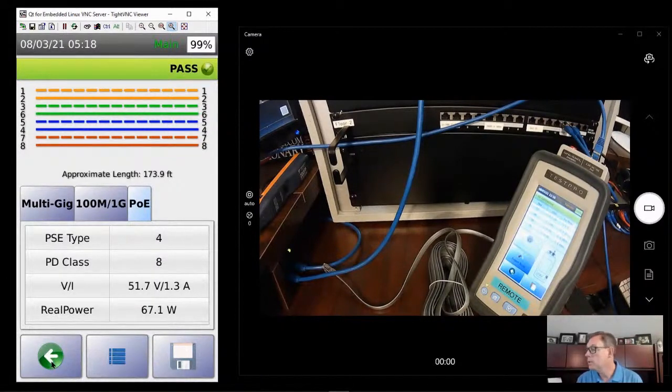And then we could do the same thing. If we ran this test with the silver satin, obviously it's going to fail. If we have a lesser grade patch cord, it would fail. But your first troubleshooting when you're having that PoE issue again comes back to that PoE tool, where you're doing a real PoE test on that cable. So that will allow you to go beyond simply pre-qualifying the cable at the time that you certify it.